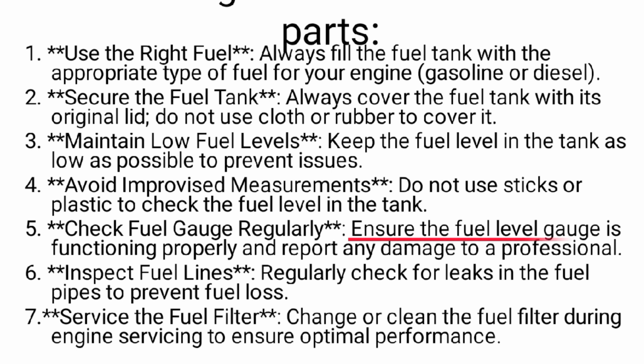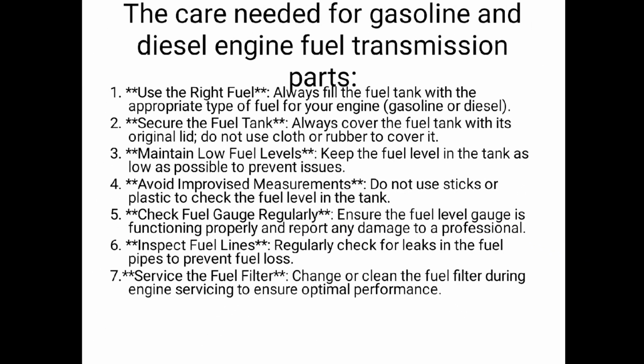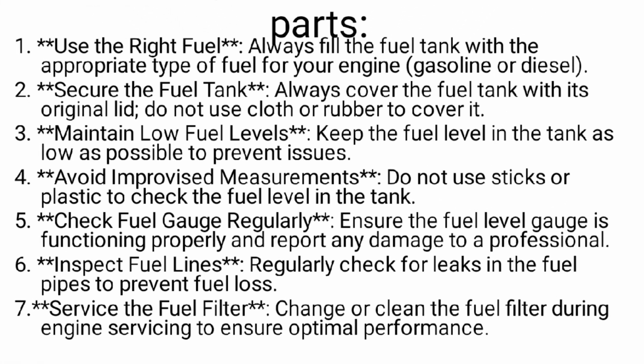Fifth, you have to regularly check your fuel gauge to ensure it's functioning properly. If you notice any discrepancies, report them to a professional mechanic immediately. Inspect fuel lines. That means regularly checking for leaks in the fuel pipe to prevent fuel loss. Lastly, change and clean the fuel filter during engine servicing to ensure optimal performance.